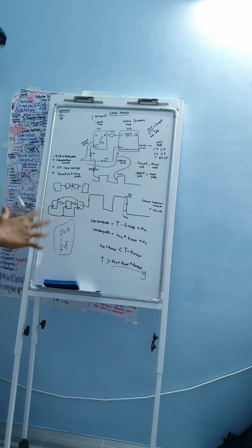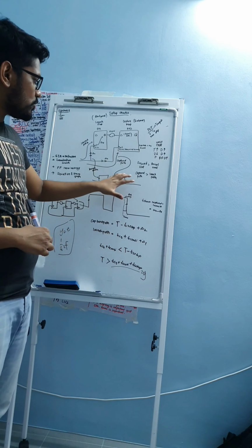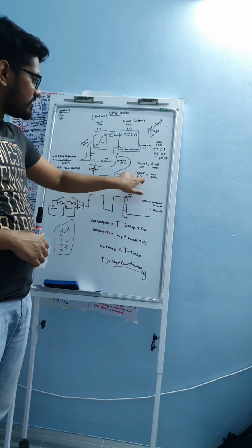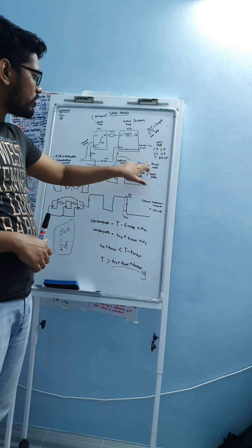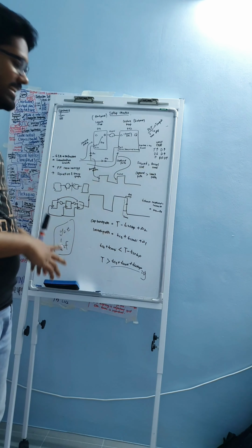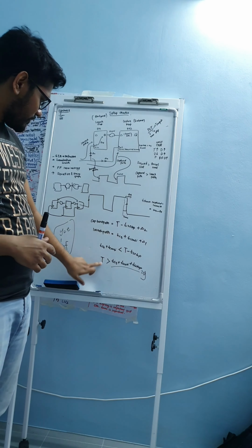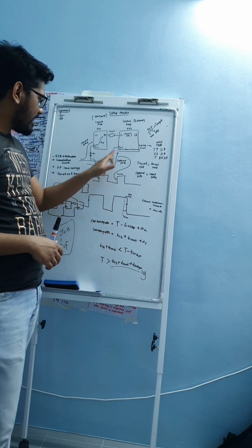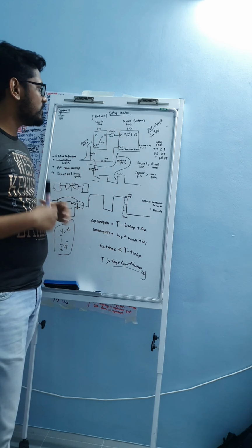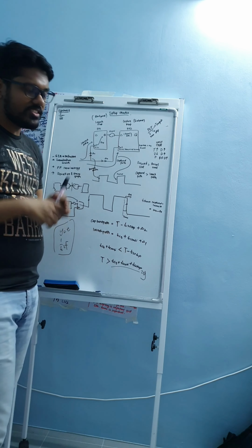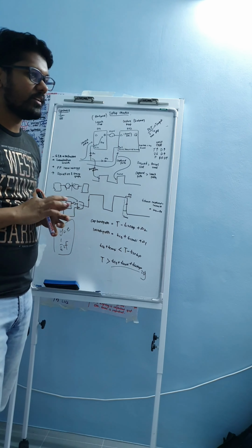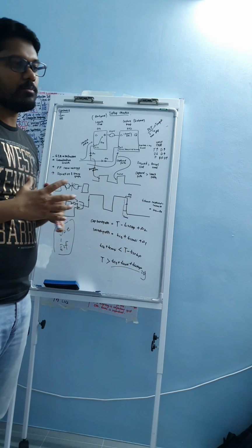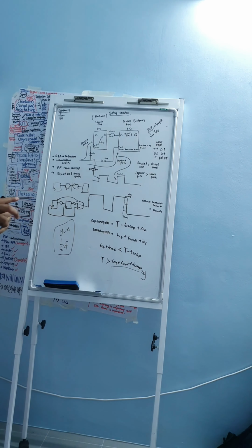The most important thing here is you have to know, making sure your capture part is more than your launch part, your required time more than arrival time. In other words, your clock period has to be bigger than your launch part. You just imagine, are you sure with this amount of time you're able to converge in the setup timing?